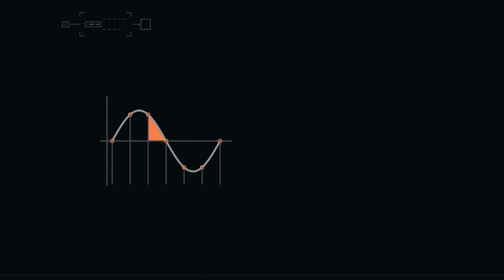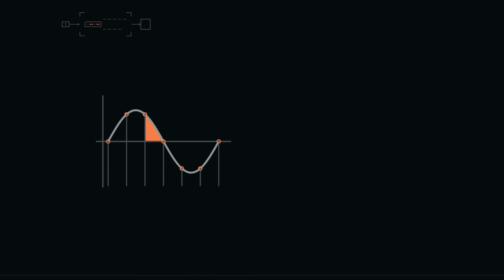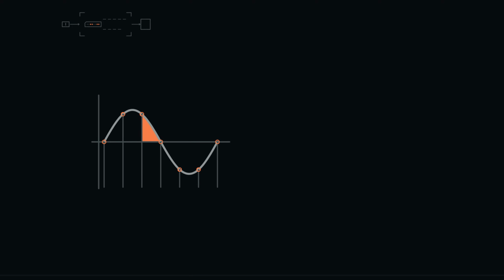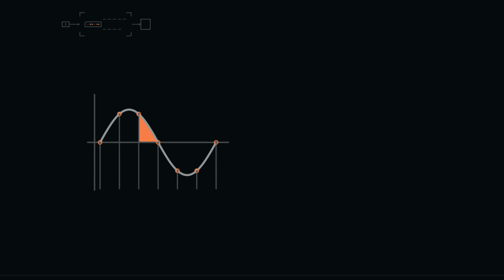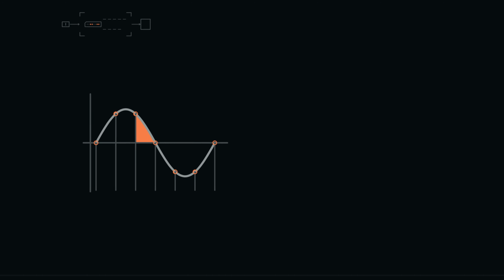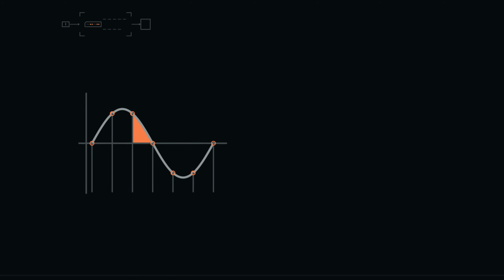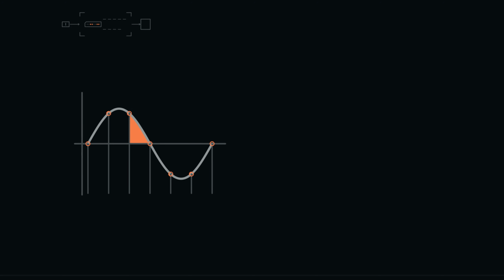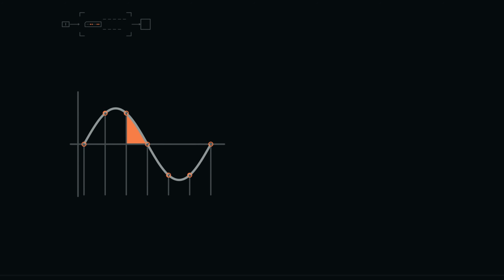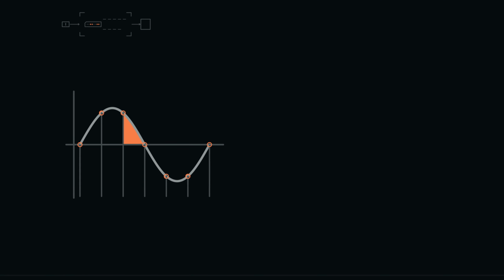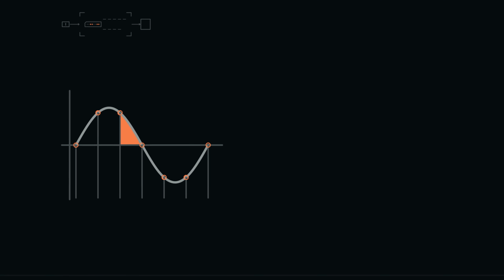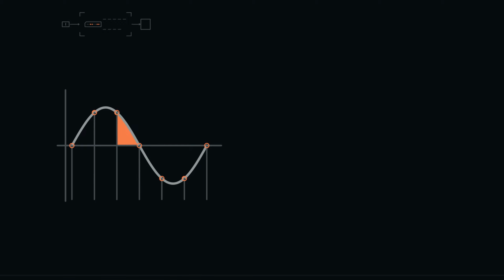Quantization selects among representable amplitude levels. A measured value between two available levels must be assigned according to a declared rule, often to the nearest level within range. The difference between the measured value and the chosen level is quantization error. Adding more representable levels can reduce that difference, but it does not add missing sample times. Quantization concerns the vertical axis.